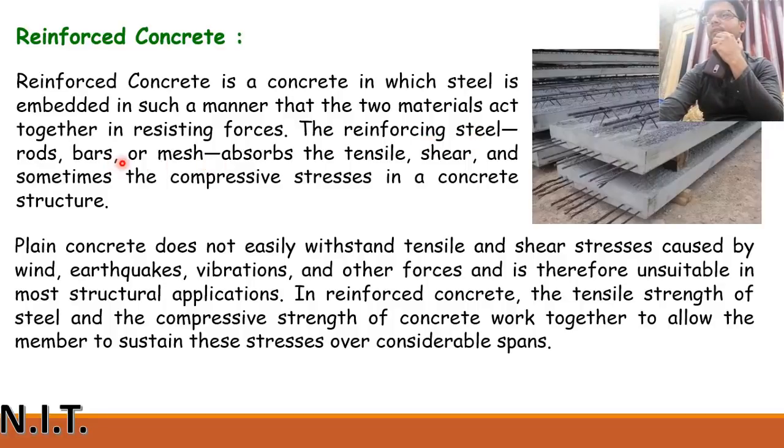The reinforcing steel rods, bars or mesh absorb the tensile, shear and sometimes the compressive stresses in a concrete structure. Plain concrete does not easily withstand tensile and shear stresses caused by the wind. Do you know what tensile stress is? Tensile stress provides elongation in a material, that is tension. You are providing tensile forces.